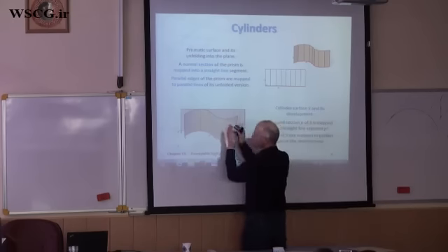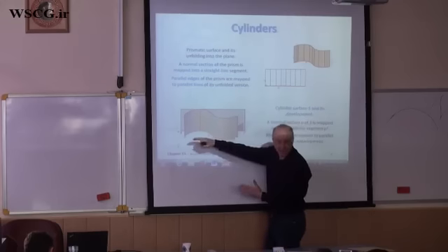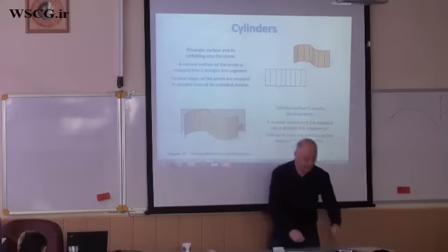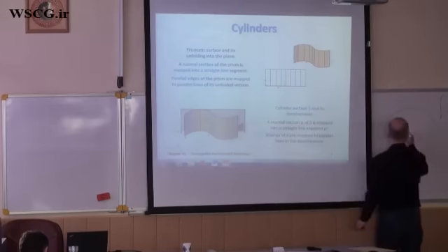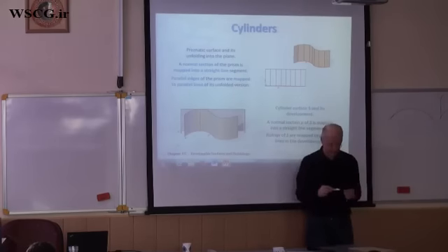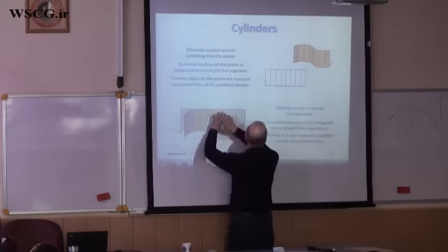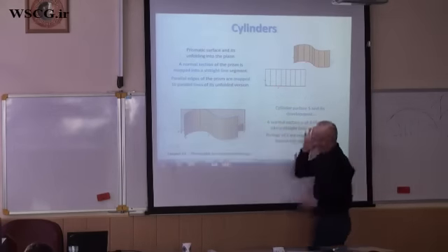Because parallel lines in the unfolding will again be parallel lines, and parallel lines in the plane intersected under a right angle, so this must be a straight line. So it is clear that the development of an orthogonal cross-section of a cylinder is a straight line.